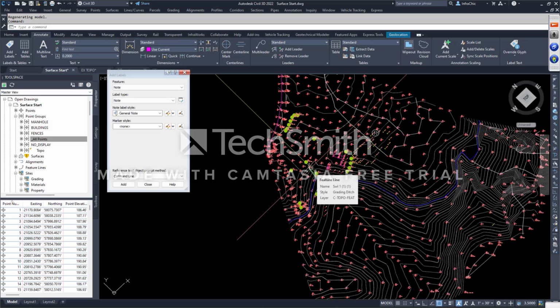So I don't necessarily have to rotate my model 45, but when I bring this model in as an XREF into a sheet file, and then I rotate that sheet in the viewport to make things fit, everything that is already set to view will automatically rotate, and I won't have to go in there and manually rotate every single little one. Saves me hours of work, and your civil designers will love you for it. So view is your favorite friend.